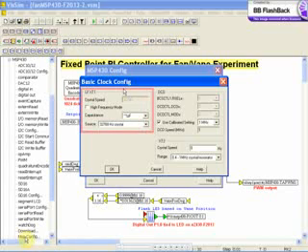The LFXT1 oscillator supports ultra-low current consumption using a 32,768 Hz watch crystal in low frequency mode. Many MSP parts in the 2000 series also support an on-chip VLO. The LFXT1 oscillator also supports high-speed crystals when in the high-frequency mode. You can configure the internally provided load capacitors to match your external oscillator. The typical loads are listed.